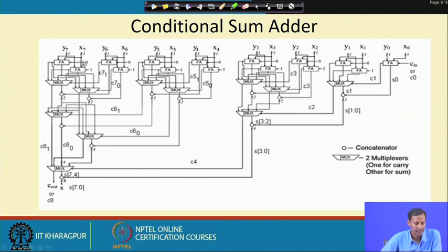Again if I choose this other path, from this input one full adder cell, then multiplexer, multiplexer, multiplexer. If I compute the maximum critical path from this cell, it is one full adder cell, one multiplexer, two multiplexer, three multiplexer.